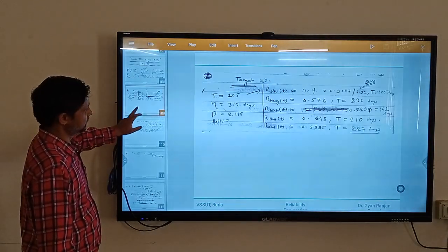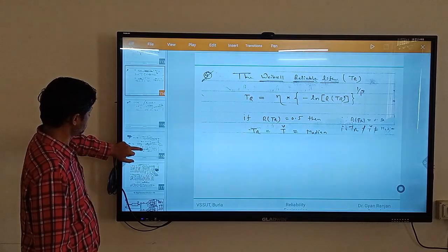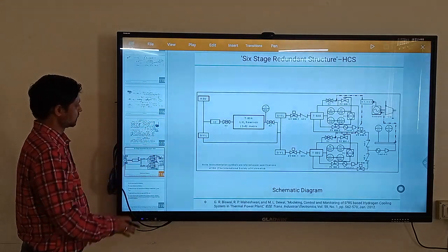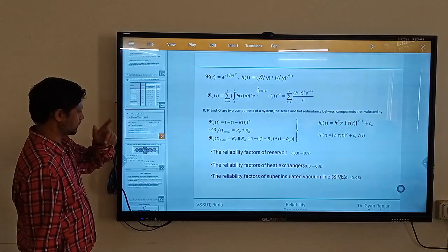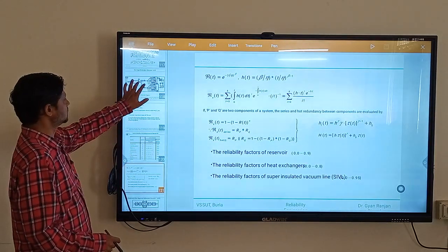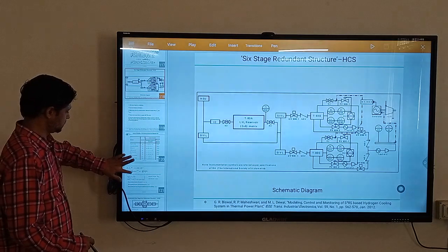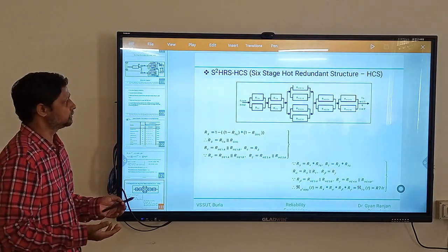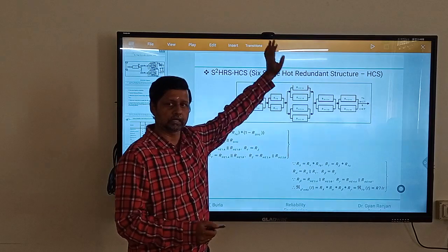Then, these things, FTA, we are doing right now. Today we will discuss this. All components are over, that is something we have already discussed. This one is system reliability analysis based on certain parameters, redundancy. That is the system reliability we discussed. Any doubt over here? That is a very critical aspect. Think over it. Remember, it is not necessary that this is the arrangement. That is basically the P&I diagram of that model, and this one is the equivalent system reliability model. To make it even more specific, we can add more and more components as critical stages. So you can say that these are my critical stages as far as that entire P&I diagram is concerned.